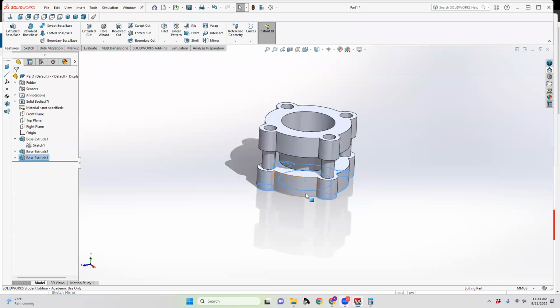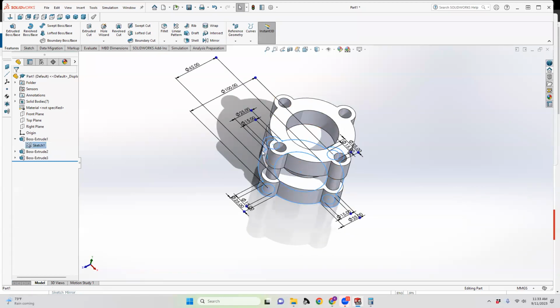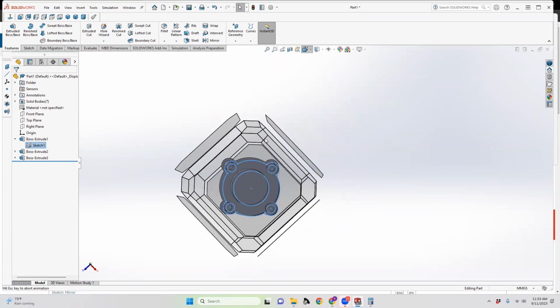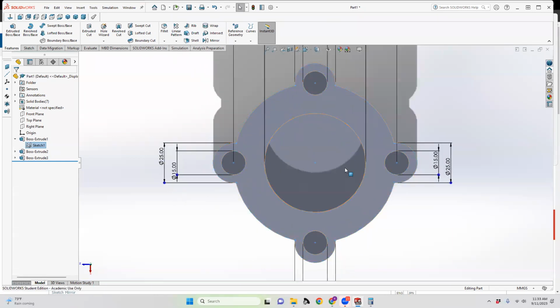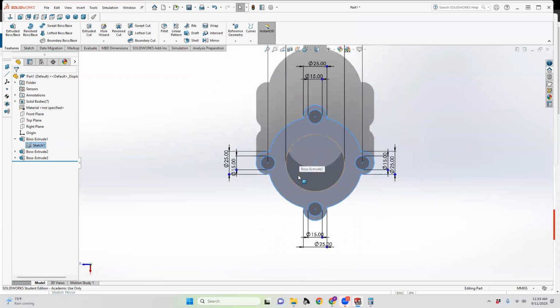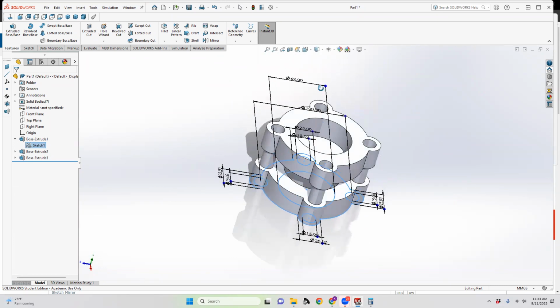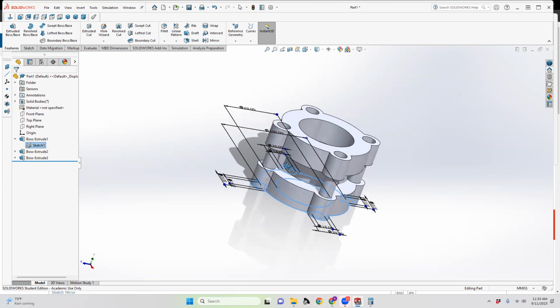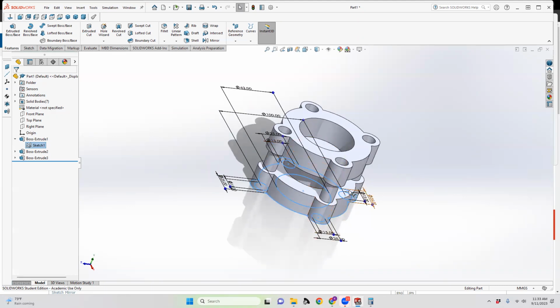You're doing something that's based on this two-dimensional sketch that we started with, right? So going back to that centered view here, that 2D sketch is the same thing that we started with, but we've now created a complex piece from that same sketch. So you can do a lot of operations on the same sketch. And here again, this is something that's going to save you a lot of time later rather than coming in, doing a new sketch each time for every single individual hole.